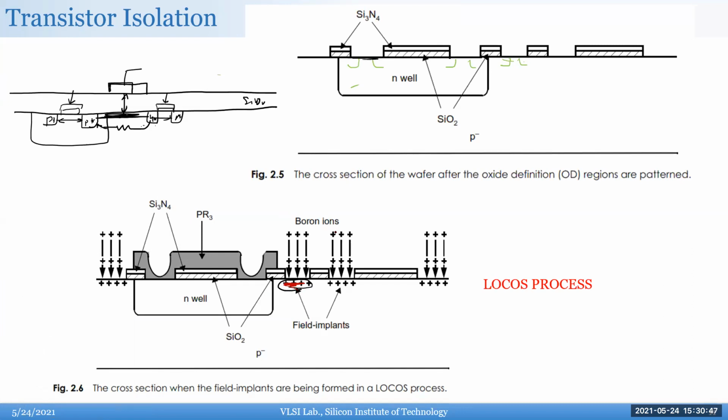For example, when I draw this substrate, I have a P plus, I have a P plus, I have a P plus. I put a gate here, but if there is another oxide here, another metal here, this is also a transistor. It's a weak transistor, but it's still a transistor, although you didn't intend to do that, right? Your next transistor was here, let's say.